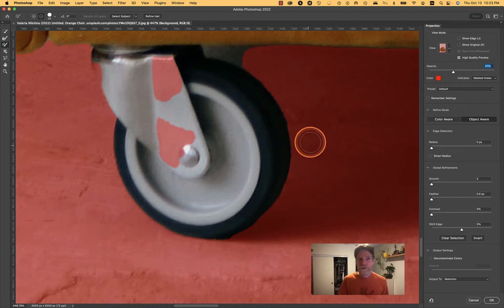It's a little bit hard to get used to what is plus and what's negative, because it's kind of working the opposite of what you expect. But what can be helpful here is if instead of going up here to grab the plus and the minus, you just hold down your Option key. The change to the tool is very small, so you'll have to look really carefully to see. But when I'm holding my Option key down, that little icon in the center is changing from a plus to a minus. So this makes switching back and forth very fast.